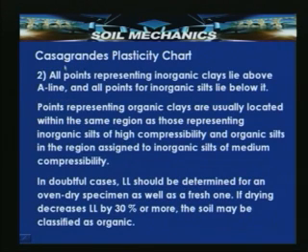So, the second feature is that all points representing inorganic clays lie above the A line, and all points for inorganic silts lie below it. So, all points representing the inorganic clays, whether low plasticity, medium plasticity or high plasticity, lie above the A line, and all inorganic silts of low compressibility, medium compressibility or high compressibility lie below it.